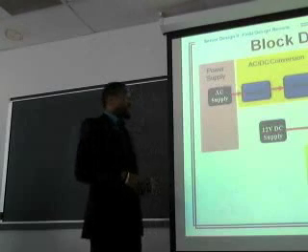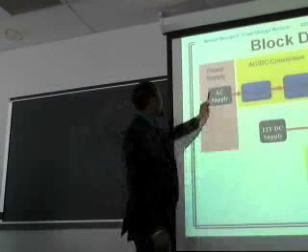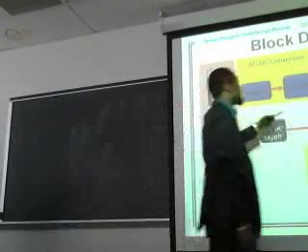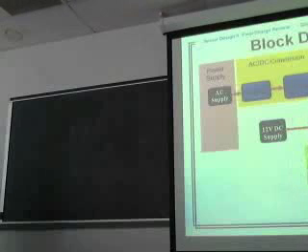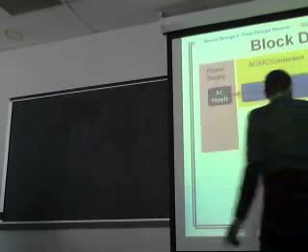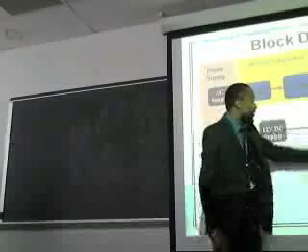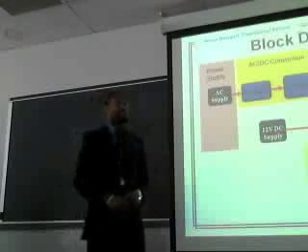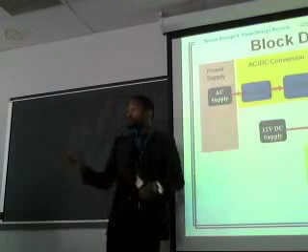And this is our block diagram. Basically, this shows everything on the overall system. You can see right here we have our AC supply. This is the rectifier that converts the AC into DC. Right here, you can see this is the load, and right here is the DC current supplying the voltage to the gate drive, and right here we have our DSP. That's a dSPACE that sends signal to the gate driver, basically. So this is basically the overall block diagram for the system.